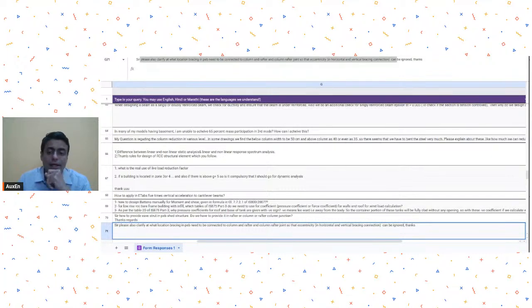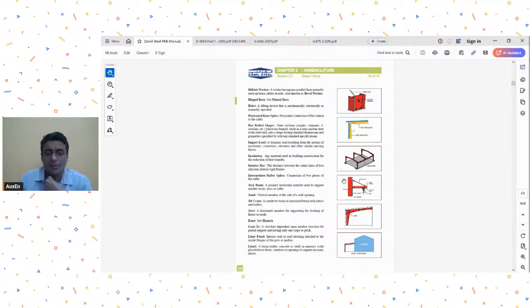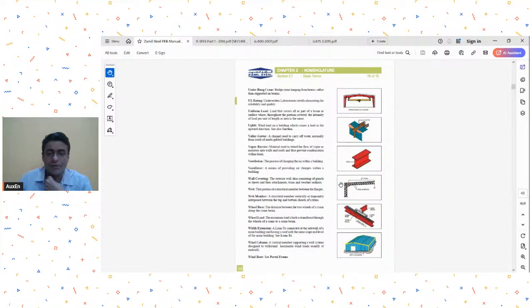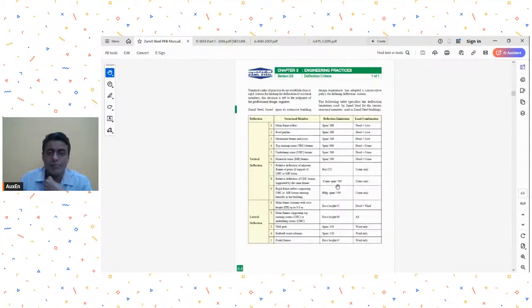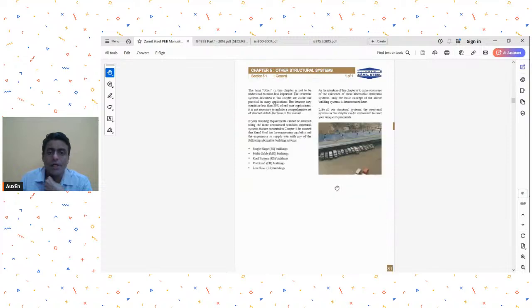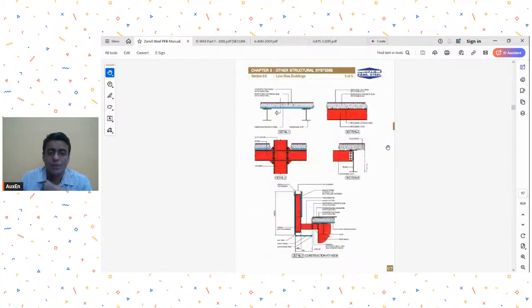So again, as far as possible, I would like to make my column rafter location free from any other connection, because then there is always this problem of stiffening of the rafter column junction that we need to do. So as far as possible, we shall make it free of that. So usually we will try and connect our elevation bracings below the column rafter junction. I'm just looking for some bracing section if I may get. This is an excellent resource, okay? You must go through it.